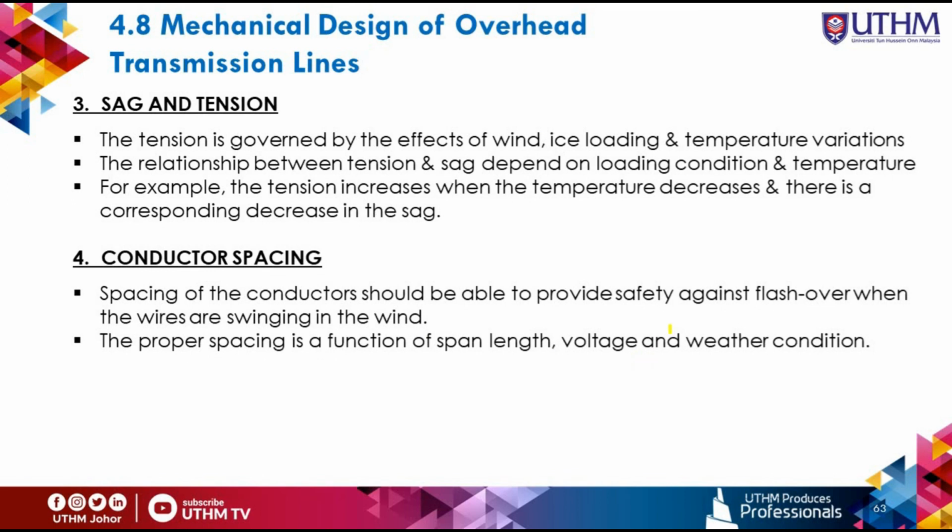When laying overhead transmission line, it is necessary to allow a reasonable factor of safety in respect of the tension to which the conductor is subjected. The tension is governed by the effects of the wind, ice loading, and temperature variations.